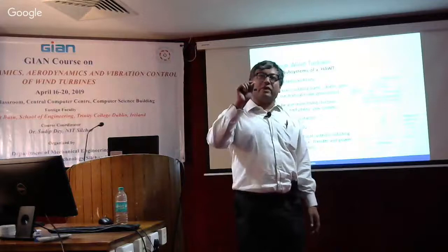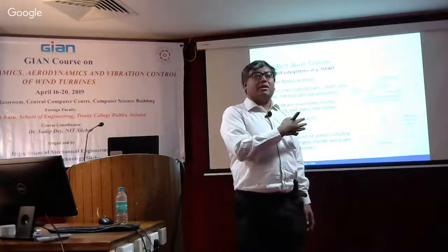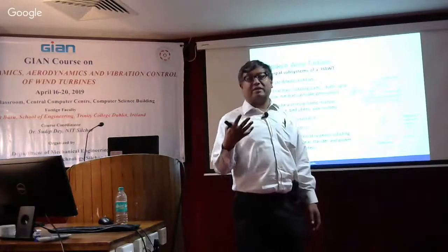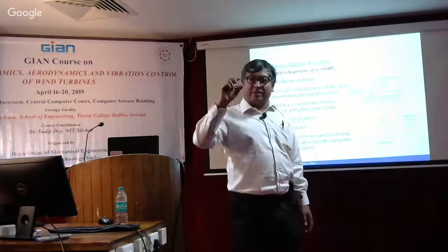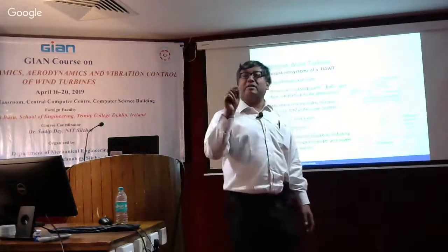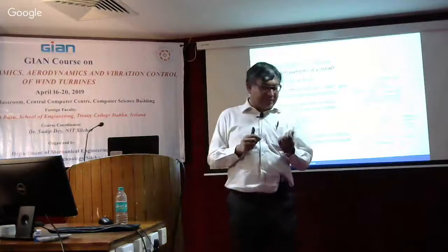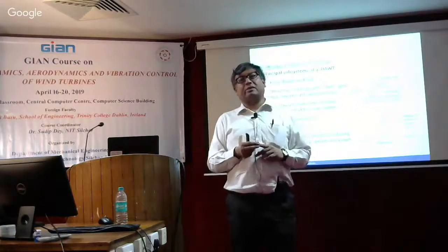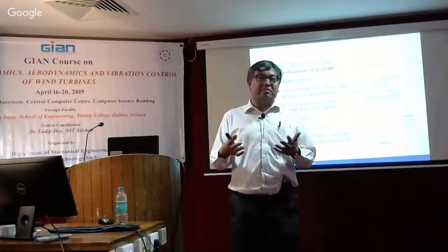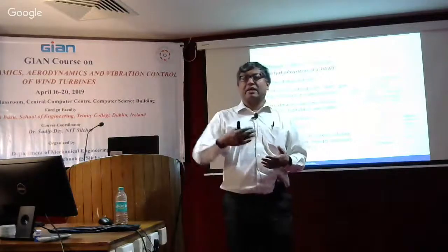Find out how much of suspended solid particles are there, and that will tell you the condition of the gearbox. Because if there's wear and tear, obviously there'll be small particles in the lubricant. So oil analysis also gives a lot of information on the reliability of the system. And then based on that, you have to take decisions. And they can be done either real time or can be sent to some data center and then information retrieved passively.